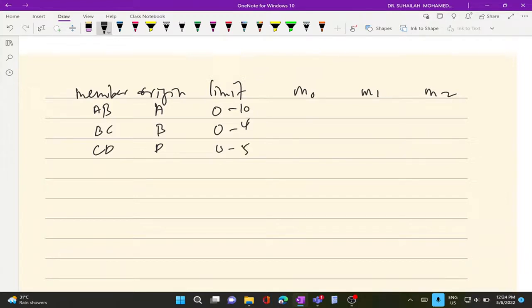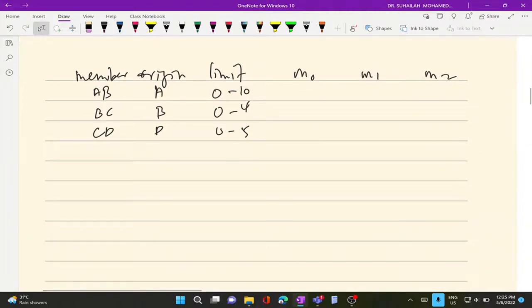So having this, you just need to substitute all the moment equations into this table. And finally, dah ada all the moment equations in the table. You need to substitute into the displacement formula, dapat displacement, lepas tu masuk dalam compatibility equation, lepas tu continue to calculate remaining reaction. Okay, lepas ni nak buat apa? Number 1, calculate displacement, 6 displacements. Calculate 6 displacements, lepas tu write compatibility equation and then solve.